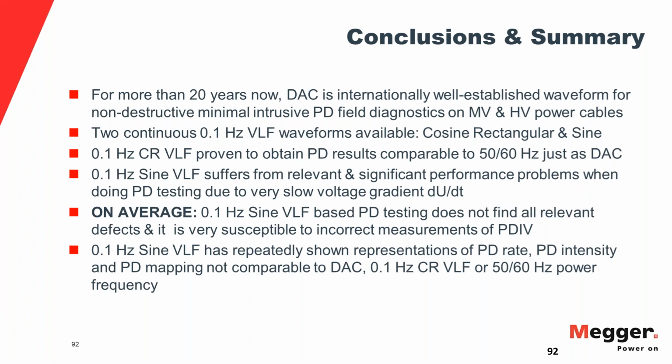And now circling back to what you just saw, if really 90% of the failures happen in accessories, and if accessories are layered interfaces, and if you do not have to worry so much about the local isolated weak spots, and you should worry about the surface discharges and the tracking and everything in the layered interfaces, you should combine the VLF testing with PD testing, and then you can use slope because it's a fully standard compliant waveform giving you the pressure test, the withstand test, and it duplicates the correct physics that will give you the right activity in the splices if there is any.